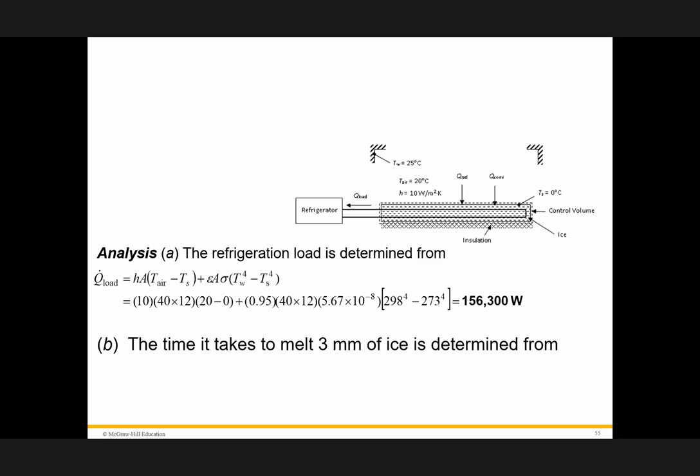Okay. Therefore, what you're saying, if I understood it correctly, this is the amount of the energy exchange. Yeah, this is from the outside. That's right, joule per second, right? Yes. You are correct, sir. Joule per second. And then this is energy exchange. Now, at the same time, we mentioned 3 millimeter of ice will be melted, as you put it correctly. Therefore, we calculate the mass of the 3 millimeter, and then what should we do with it? Well, we have the latent heat of ice. Absolutely. That's right. So we can use the mass times this to get the energy.